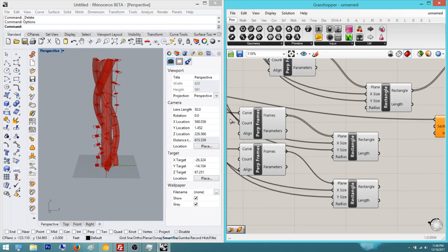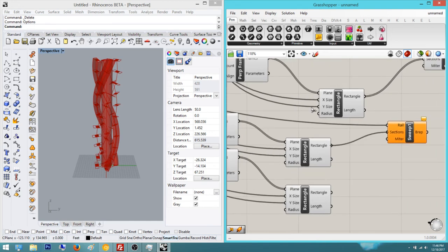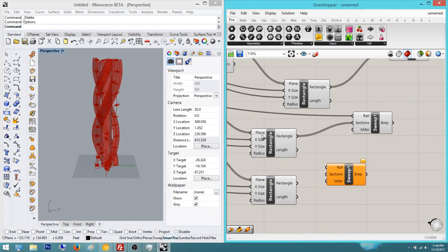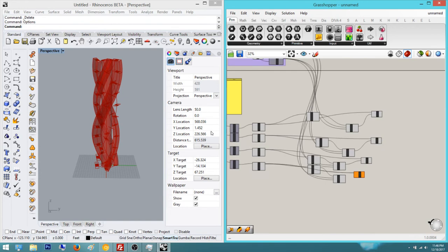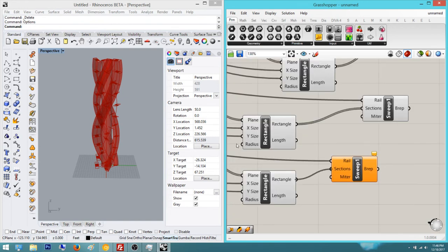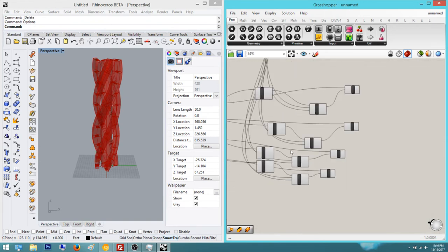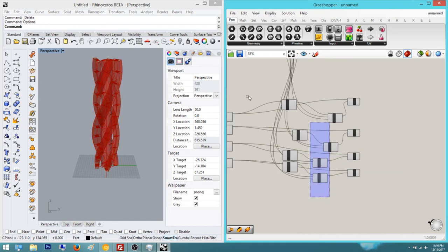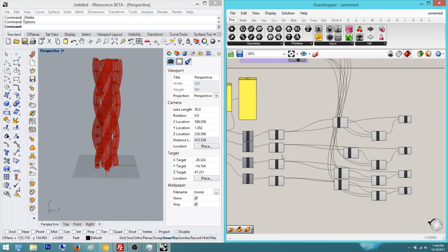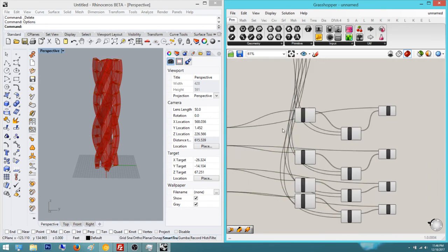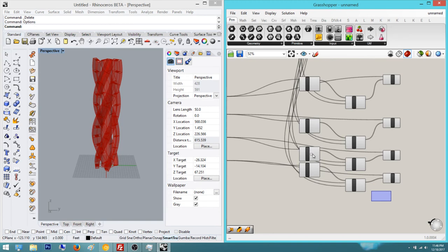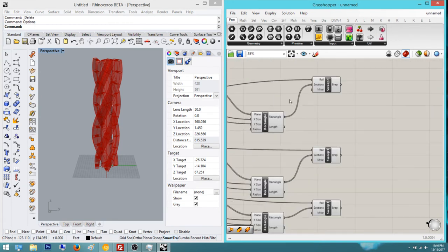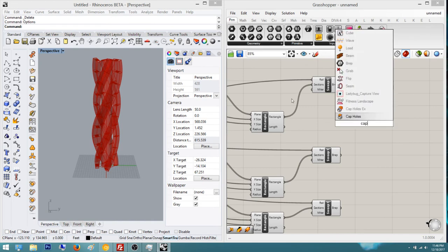Boom. Boom. And then this one. And then finally, we're going to put the railing onto this last curve and section this curve. Alright, sweet. So we have everything kind of not organized, so we're going to align everything. Nice. It's somewhat organized now. Yeah, at least all the sweeps are in one area. And now we can do cap holes.